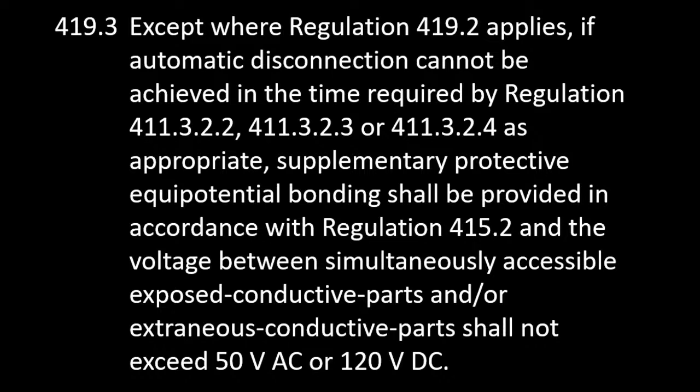Yeah. So as you said, Dean, that 419 section has been broken out now into the 18th, so it's far more apparent. It was always in there, but it was kind of hidden amongst the regulations, and it's the case whereby you will disconnect. So in the example in the question, the person's 100 amp fuse will disconnect eventually. It perhaps just won't disconnect within the 5 seconds disconnection time required for ADS.